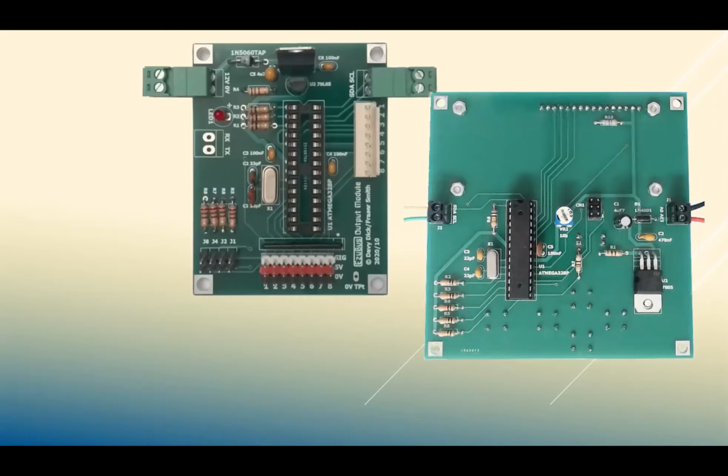You don't have to use the nanos. I used nanos initially for the EasyBus output modules, but you'll see there that we're using the 328 Atmega chip without the nano, mounted on a PCB with its own voltage regulator and its own pins and its own crystal and so on. The right-hand side, again, is using an Atmega 328 chip, not the Nano, just the chip itself with all its surrounding bits. That's to make up the new EasyBus controller.